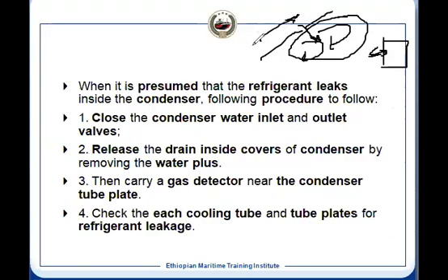So suppose there is a throttle valve. There will be a hissing sound passing, and we can actually hear that sound, but this is for the leakage. If there is a leakage and we can hear it, then we can detect it by our five senses. But this sensor will detect the turbulence sound which we cannot detect with our ear. Understood? It will detect that wavelength. Suppose there is a throttle and some sound is generating, we cannot hear it.